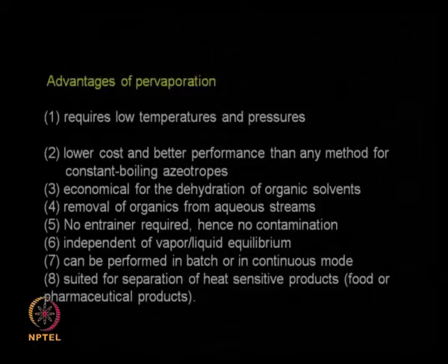It is very economical for dehydration of organic solvents. That means I want to completely remove all the water present in solvent. So what else can I do? I may use a distillation, that is energy intensive, and sometimes you might not be able to get 100% dehydrated solvent. So what else can you do? You can add some adsorbent which will absorb water or moisture, then you have to filter out that adsorbent, and then the adsorbent has to be heated again so that it gets regenerated and ready for further processing. Okay, so it is going to be 2 or 3 steps.